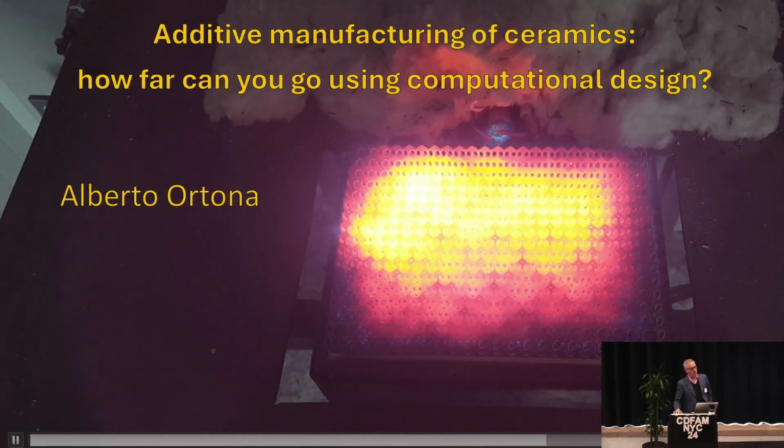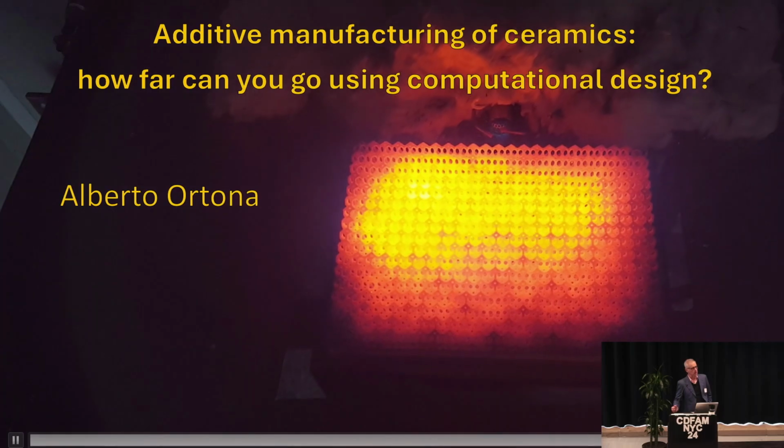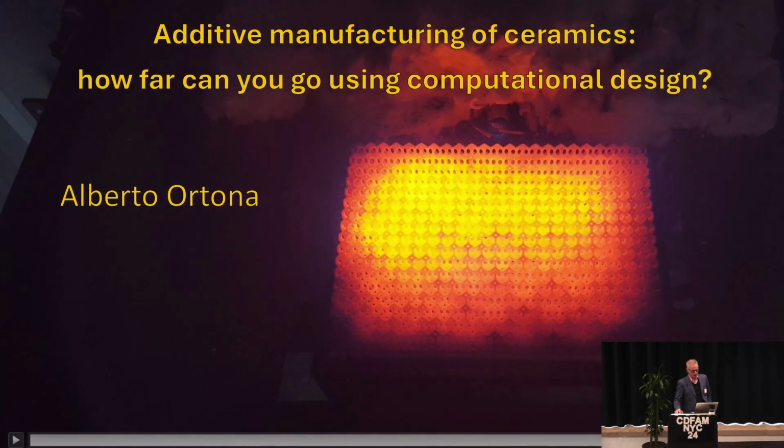This is a porous burner. So it's a burner in which the flame is constrained within its porosity. And of course, to have this component running, you need a material that withstands very, very harsh environments. And by that, I mean temperatures around 1300 degrees C and oxidative environment. So these are highly engineered materials, both on the materials themselves and on their topology.